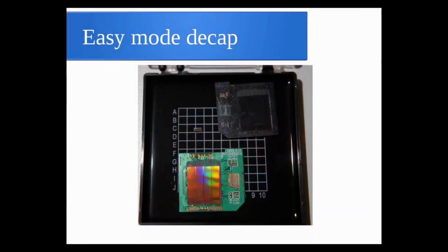One sort of interesting thing is, of course, I like to take apart stuff and see what's on the inside, so we wanted to decap some chips. Some of these overmolded chips are actually really poorly constructed. My instinct was to go find some nitric acid, get safety gauze and a fume hood and everything like that to digest these. Zobs was like, I don't know, I think you can just take this off with a screwdriver. I'm like, nah, you can't do that. So he starts playing with it and flexing it, and the top just pops right off.